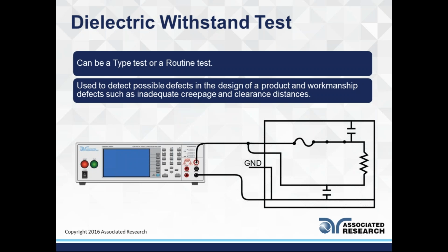What's that mean? So let's look at this diagram here, or a schematic if you say. You see two capacitors here. I don't want that to be misleading. When I short my line and neutral, as I have here, and I apply high voltage to it. Now when I say I apply high voltage to it, voltage is always referenced by 2 points, right? So my line and neutral has now become 1 point, my high side, my red, my hot side. And now my return, or my reference, my zero, my low, is on my ground circuit.